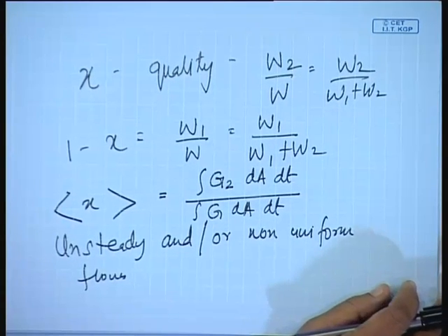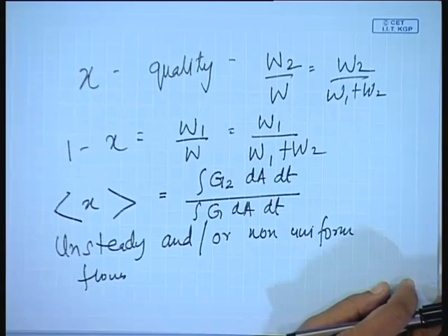Now, remember one thing, just as we were discussing the flow patterns for a heated tube, we had inserted pure liquid at a temperature just below the saturated temperature, and as it was flowing up, it reached the saturated temperature, vapor started forming, and then we had bubbly flow and so on and so forth.